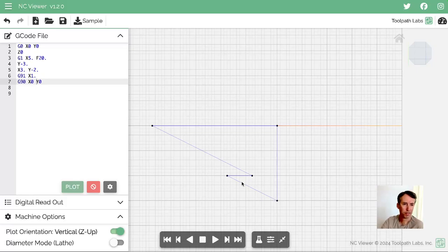It's nice to know them, but as a beginner, it's easy to get in this mindset of G91 where everything is incremental and you're moving from this location out a certain distance. So if you're having troubles with your program, that's another thing I would urge you to look at: are you thinking in absolute or in incremental? Because you should generally be thinking in absolute, not incremental. All right, so we're going to end this video here and continue this series in the next video. Thanks for watching.